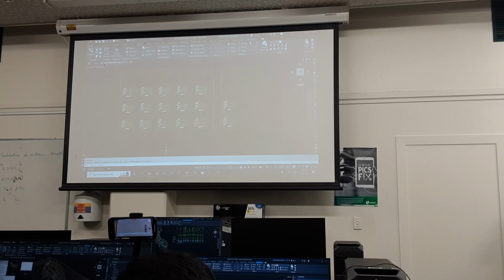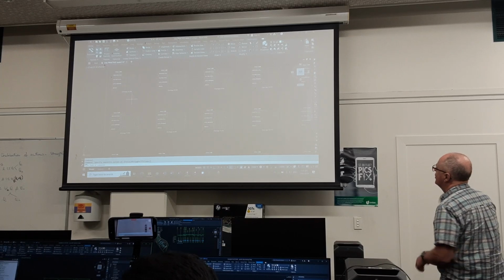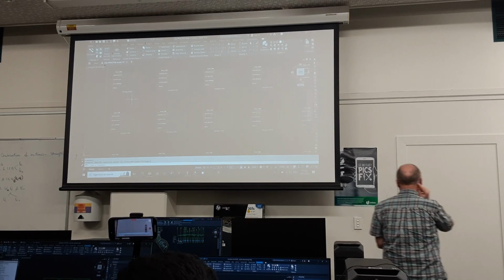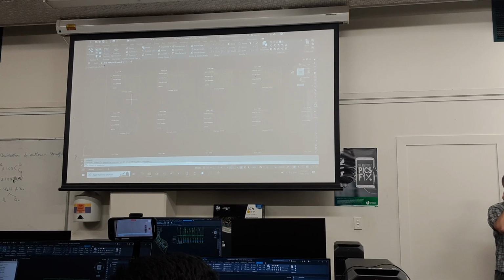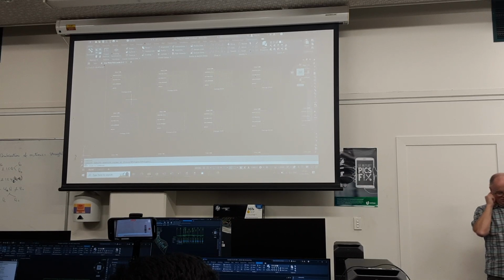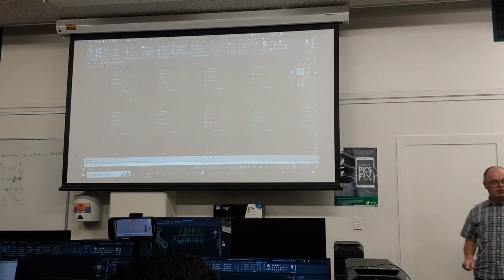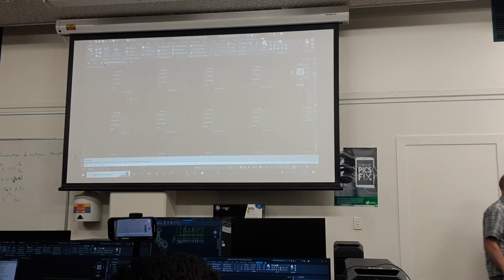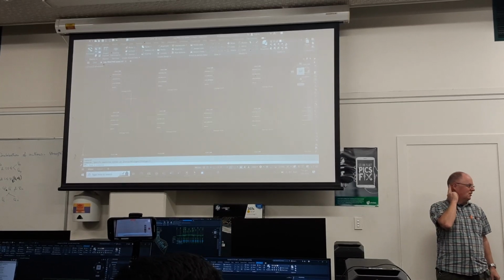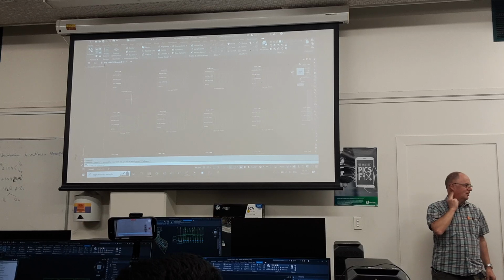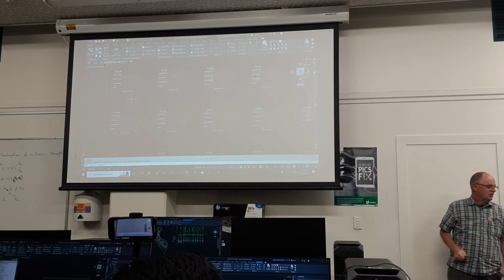Notice it's got chainage there, that's important for road cross sections. The chainage is a survey term, kind of weird. It's what surveyors use. What we used to use were survey chains. They used to actually pull chains, 22 yards long. I actually did that in my very first training for surveying many, many years ago. And you had a weight, and it would have a reading of how much pressure you pulled on it.